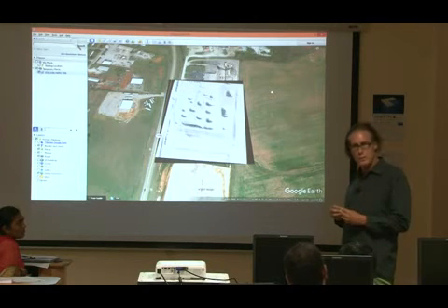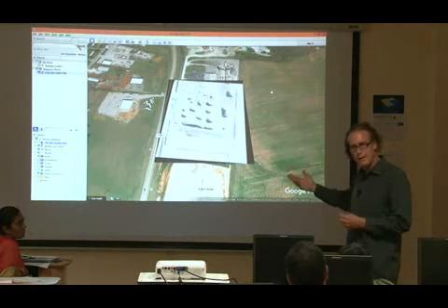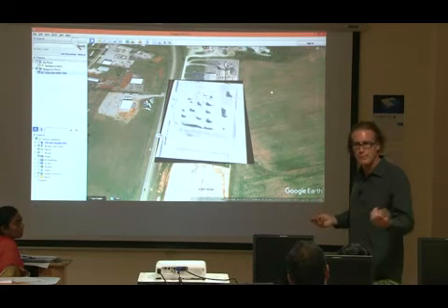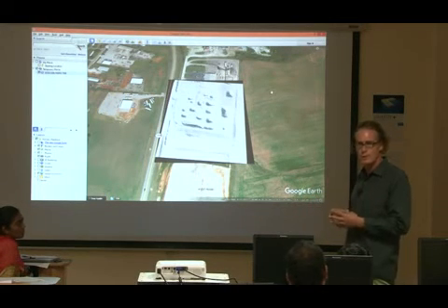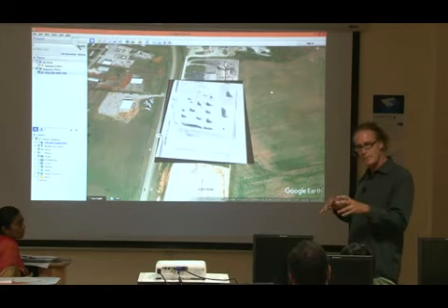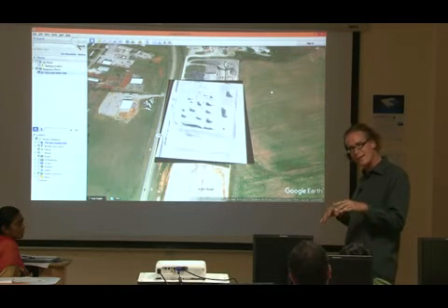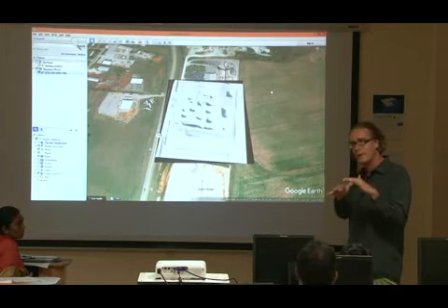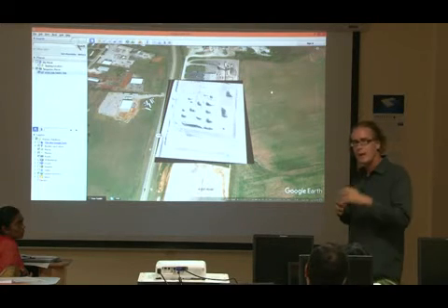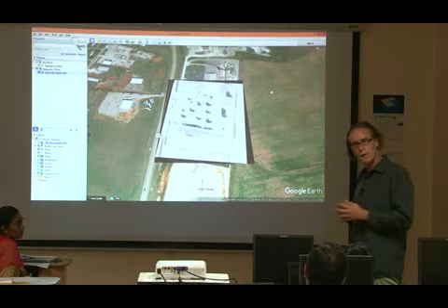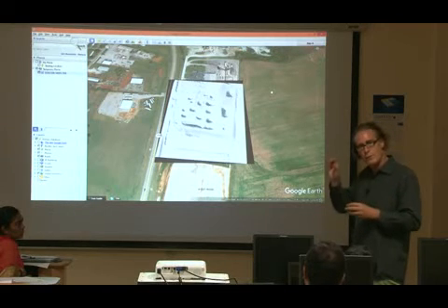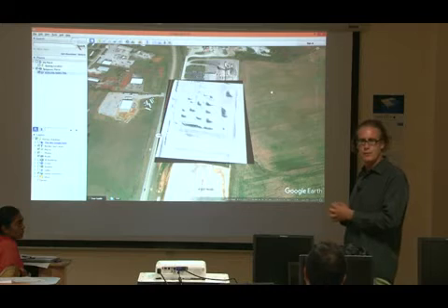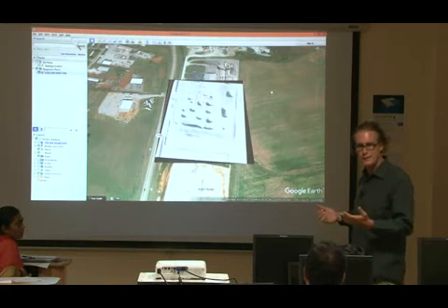But do I use right now in my lasclassify the fact that green points are more likely to be vegetation than red points? No, I don't make use of that information. You can make simple rules with lasclassify, because you can make simple filter rules. You can say whenever the green value is between 128 and 153, and the red value is below this, then set it to vegetation class.